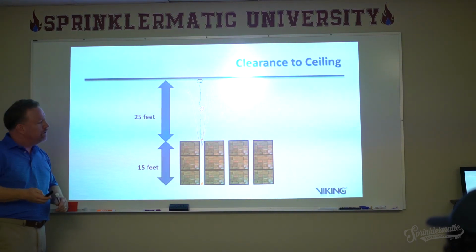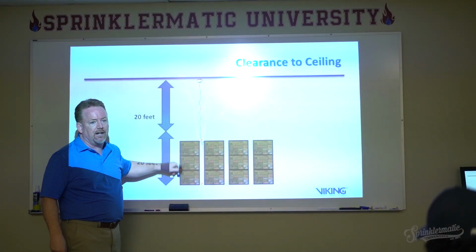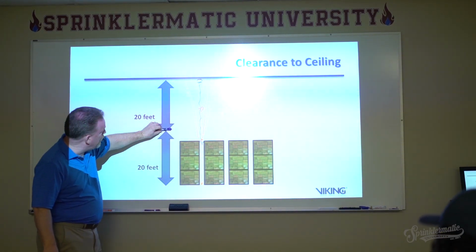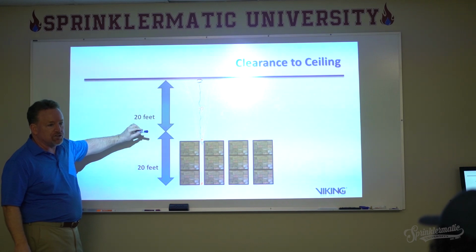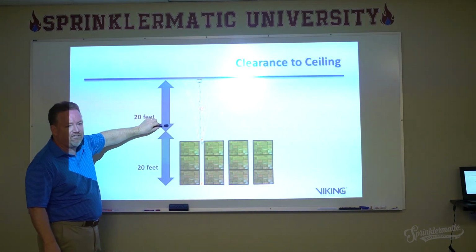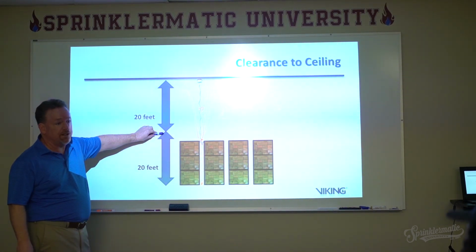Not necessarily. So what we have in NFPA 13 is a limit to the open space above storage. Even though the owner is saying, I've only got 20 feet of storage, the designer is going to be required to design as though there is this phantom storage up here up to 20 feet. So right here I would have to go to what? 25, right?